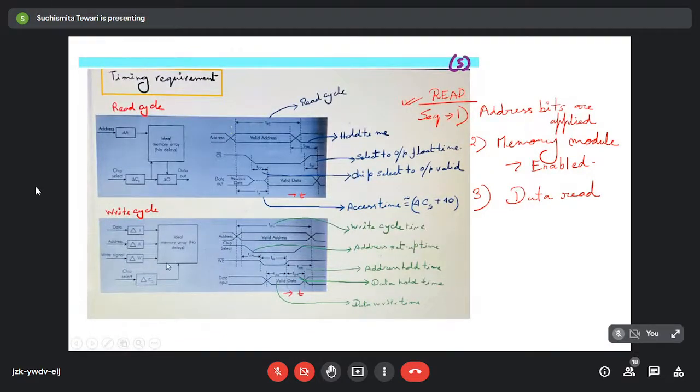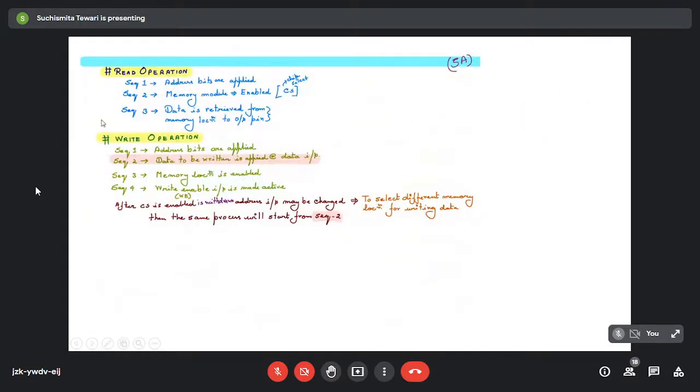Now here also we can see this entire write cycle in the form of a block diagram. In addition to the address lines, a data line is inserted, and the corresponding delays associated with these lines are represented by lumped elements and given names like delta I, delta A or delta CS. So this is the timing requirement of the read operation and write operation in detail, that is, what signal has to be given after what. This is how the entire operation is done.